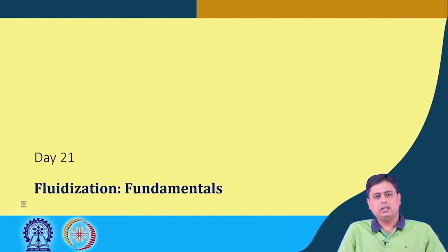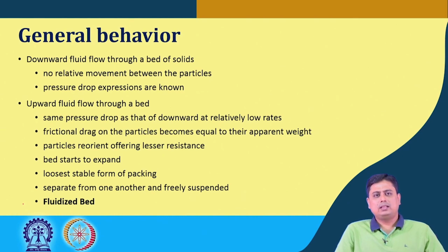Now the point here is that when there is downward fluid flow through a bed of solids, this concept we have cleared pretty much. Over the last week we have seen several expressions for how to calculate pressure drop through such a flow system when there is a downward flow through a bed of solid particles, fine particles, irregular shaped particles.